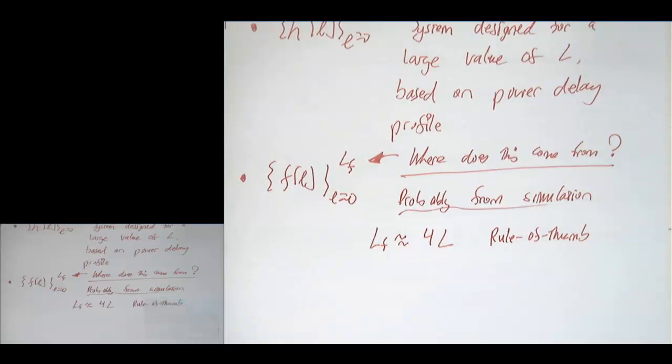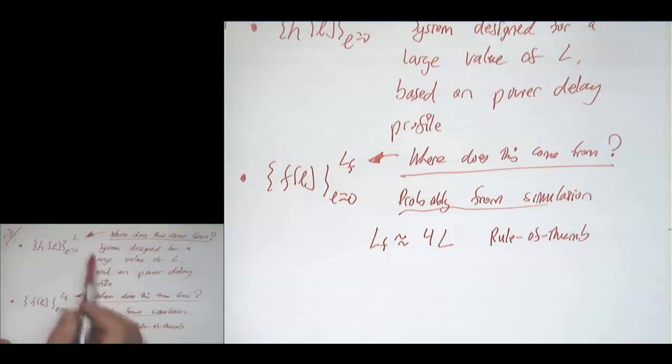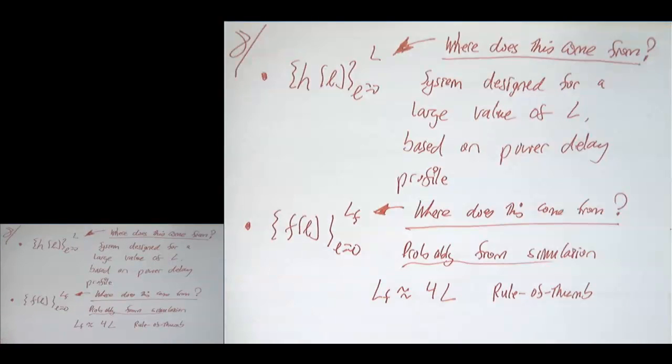And so if you work in engineering any kind of a wireless system, there will be some channel measurements and some channel models. So there'll be essentially statistical models for this quantity here. And these might be, like in GSM, models for urban areas and rural areas and suburban areas. So you could imagine simulating all these different models, trying different equalizer orders, and figuring out which one gives you some good performance on average.